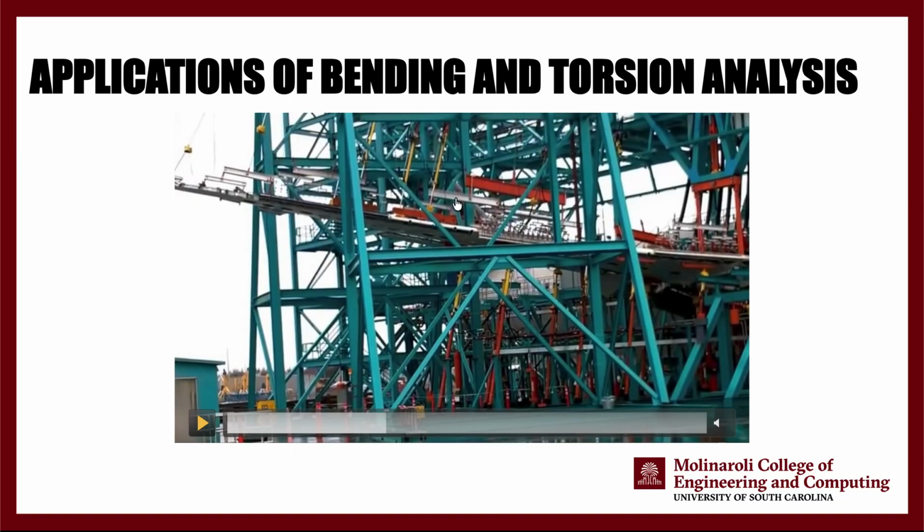As you can see, there are rods connected to these I-beams that are applying the load. The reason we have these I-beams is because we want to simulate the uniformly distributed or non-uniformly distributed load that is being applied to the wings here. So that's why we have the I-beams, and that's why we have different levels of them.